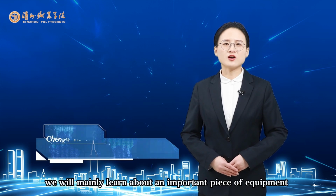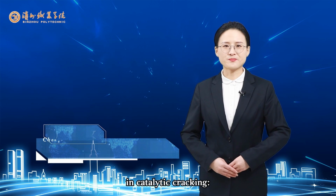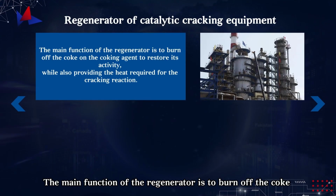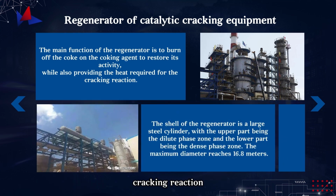Students, in this lesson, we will mainly learn about an important piece of equipment in catalytic cracking. The regenerator. The main function of the regenerator is to burn off the coke deposited on the catalyst, thereby restoring its activity. It also provides the heat required for the catalytic cracking reaction.